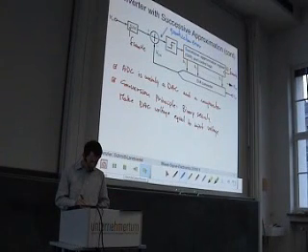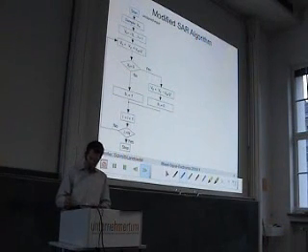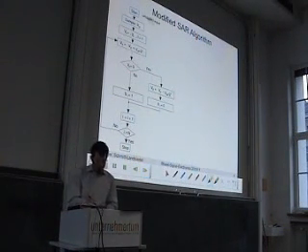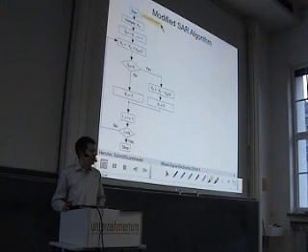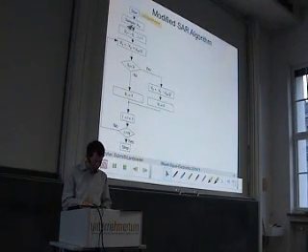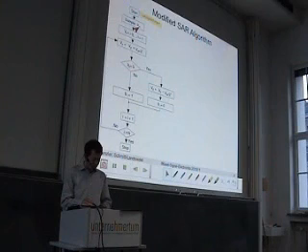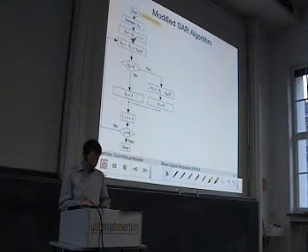In order to go towards the implementation of such a device, we use a modified SAR algorithm, which is basically intended for unsigned signals. You can extend this to signed signals, but here I will explain it for unsigned signals. The first step again is to sample the input voltage. Then we generate an auxiliary signal which is called Vx, and this Vx is simply minus the sampled input voltage. So we say Vx is minus Vin.